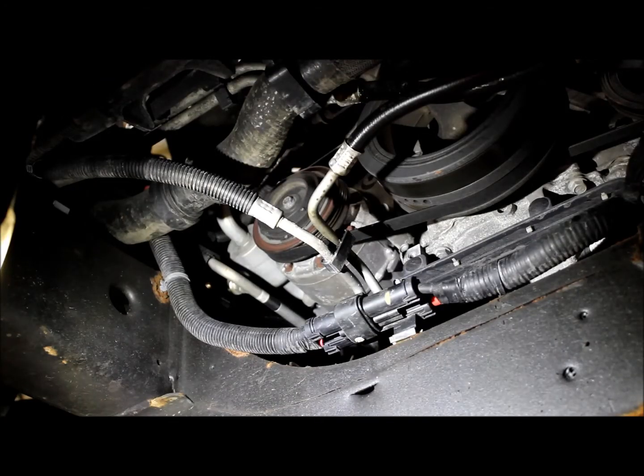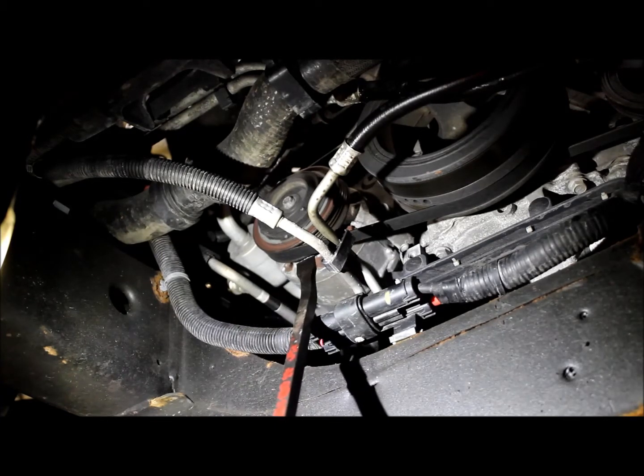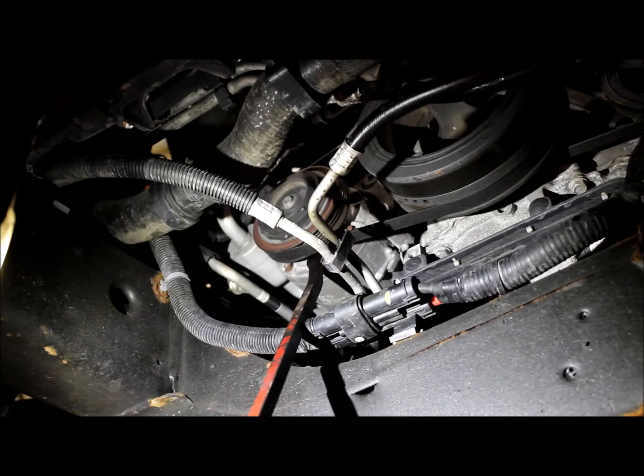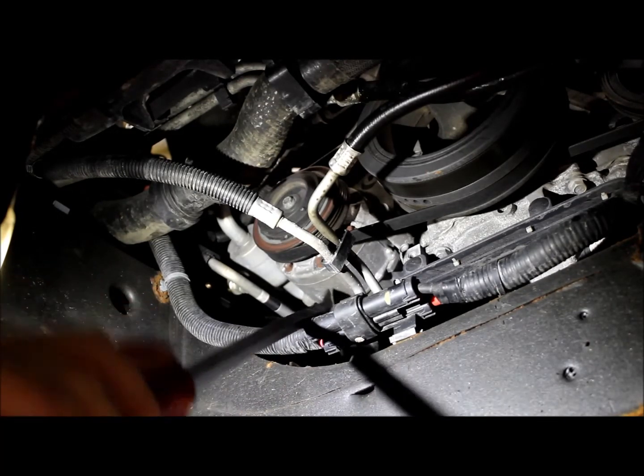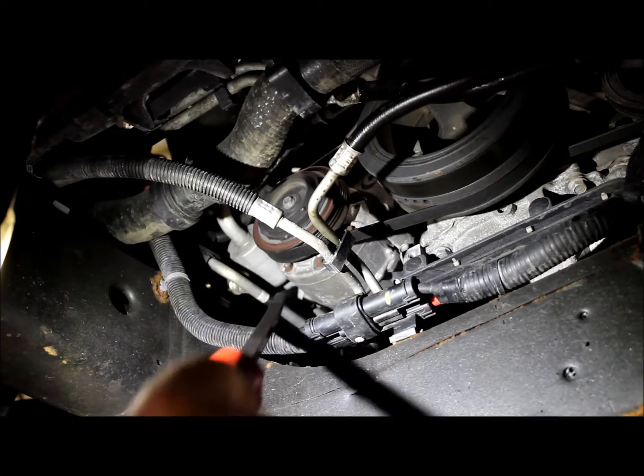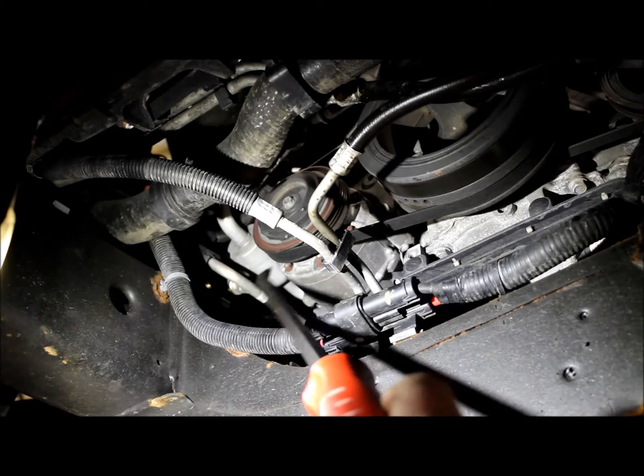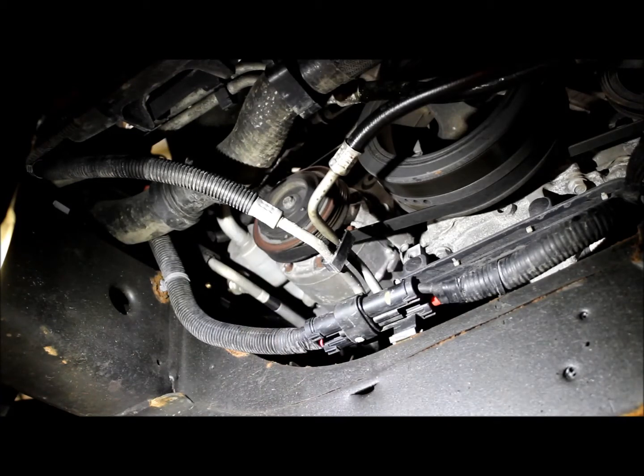I've put the vehicle up in the air and removed the bottom shield so we can see the AC compressor here. Here's our compressor clutch, AC drive belt, the compressor itself. And what we're looking for with the visual inspection is a leak. So obviously any signs of oil coming out of that front compressor seal, the body, the lines on the back here, which you may not be able to see in the picture, or the lines that come in and out of the compressor.